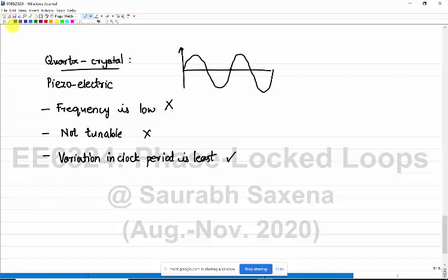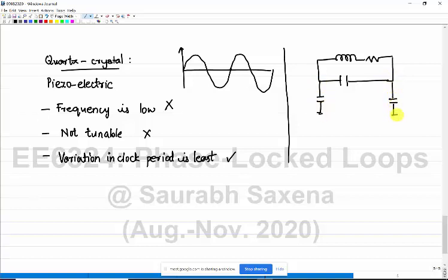Okay. So what we see is there is an electrical equivalent of the crystal. And what is that electrical equivalent of the crystal? Electrical equivalent of the crystal is an inductor. And you have a capacitor also associated with it. Inductor is a real system, so it is going to come with a resistor, and then you have a capacitor connected with it, and then you may have other parasitic capacitors connected on the side. This is just an equivalent of a crystal, nothing more.